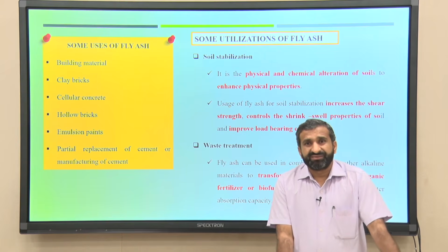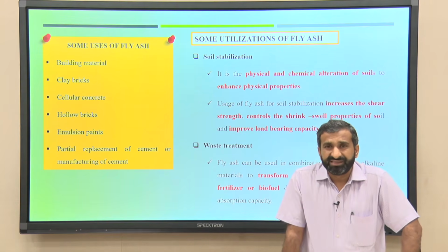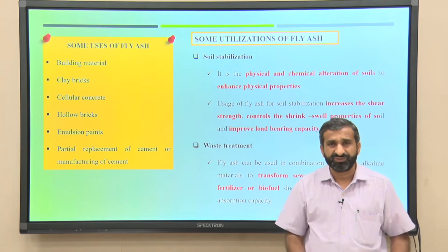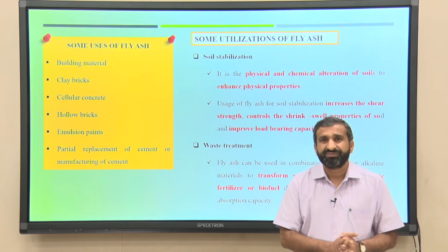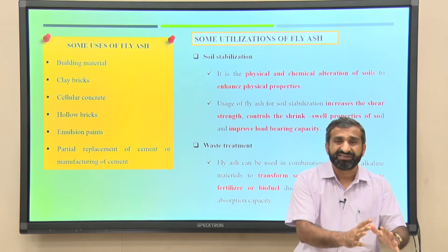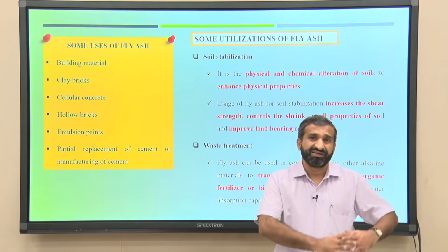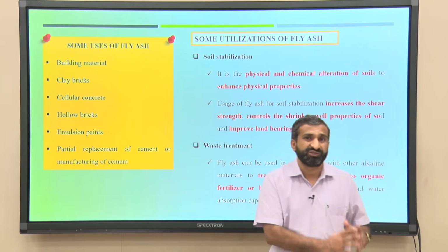So, when you are planning an incineration facility in any city, especially in India, you need to look at two important environmental issues. One is flue gas, how best you will be able to treat that. Before having the incineration facility, a flue gas treatment facility or air pollution control facility has to be installed.